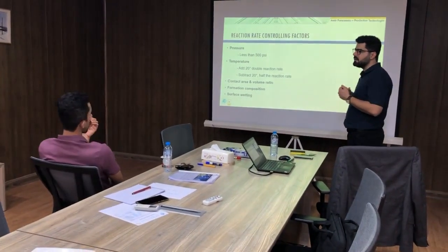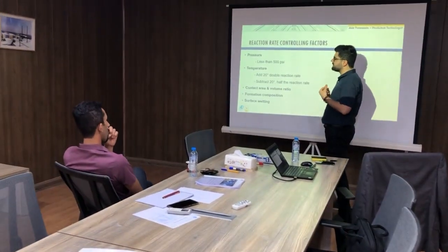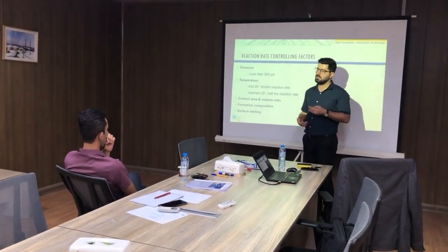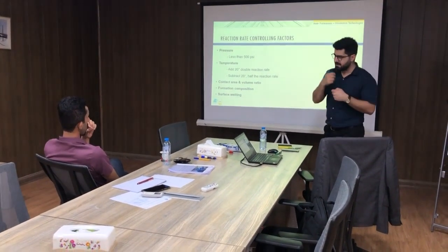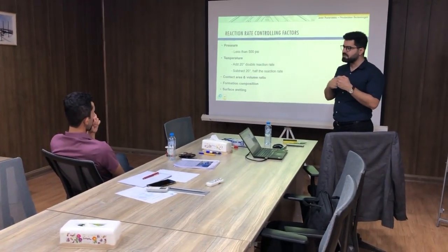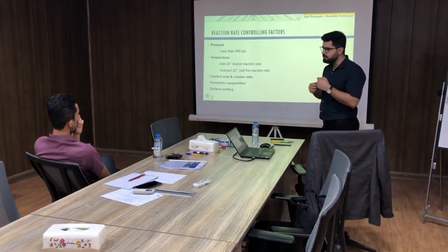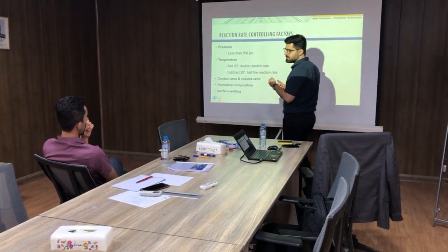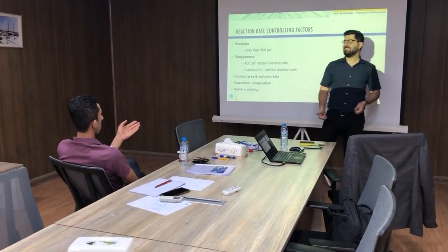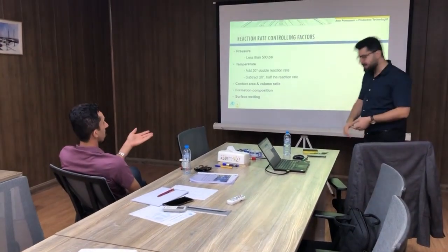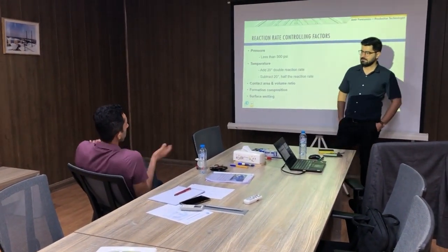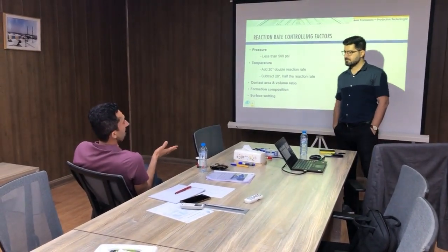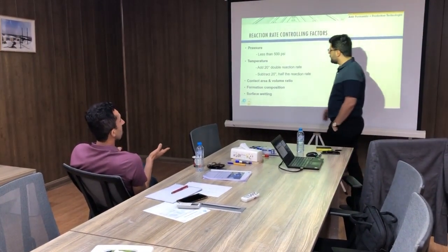You cannot put 28% of HCl to a high temperature reservoir. You should retard this stimulation. You use retarded materials to control this reaction rate, because of the high temperature there. Exactly. So high temperature doesn't require high concentration. Exactly. Yeah, but the equation says adding 20 degrees. How can we add 20 Celsius to the reservoir? We cannot, right? Yeah. So it's not in our hands.